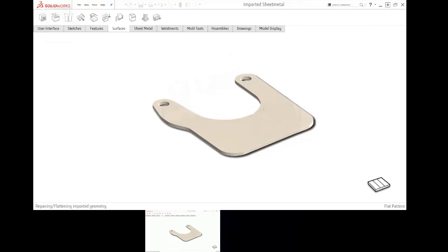Okay. Is that what delete bodies keep is? So when you go to delete bodies, you have the option of deleting it or keeping it. That's another one of those language things that always confuses me. So you're deleting it, but you're actually keeping it around for future? I would not have done it. Now this just had one solid body. Yeah. So delete bodies deleted the one thing that was there. Right. In my case, if I wanted to retain that body for comparison purposes, I just wouldn't have done the delete body command at all. I just would hide it. To your question about when you use the delete body command, there's an option to keep bodies.